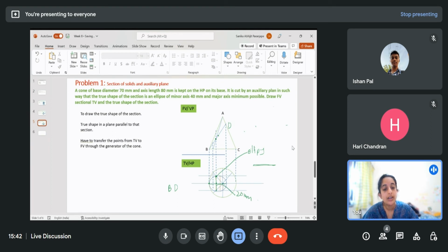And I had assumed that this is the minor axis, but this is not the minor axis. So you cannot randomly choose some point in top view and call it the minor axis, because any line like this is not going to be a minor axis of the ellipse. The points will lie on the ellipse, but it could be a line here, it could be here, here, or here.